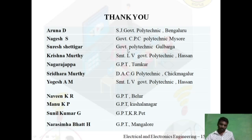If you recall the concepts of this particular session, we have seen the working principle of the DC generator, how AC voltage is generated in the armature conductors based on Faraday's laws, and how that AC voltage is converted into DC voltage with the help of the commutator, also called split rings.